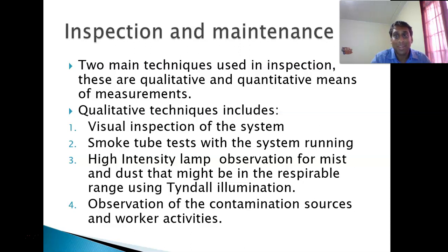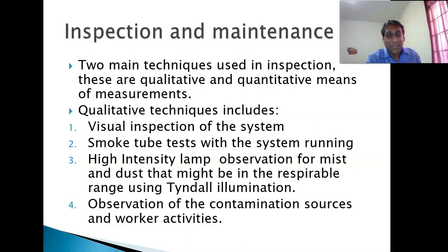maintenance: the two main techniques are qualitative and quantitative. Qualitative uses visual inspection, and putting it very simply, someone could do a visual inspection of the LEV system. They can look for defects. They can look at the exhaust, where the contaminants are coming out, to see if contaminants are really coming out.